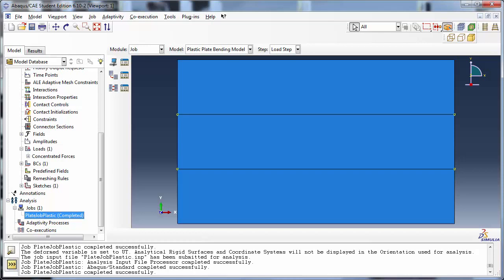When performing a restart analysis, the model must be the same as the one used in the original analysis up until the restart location. This means that any geometry, materials, steps, loads, boundary conditions, fields, interactions, and meshes defined in the original model must not be modified. New sets and amplitude curves may be defined in the restart analysis model.